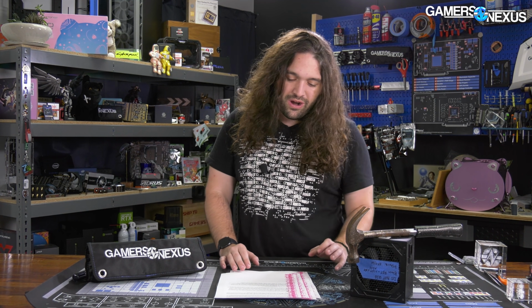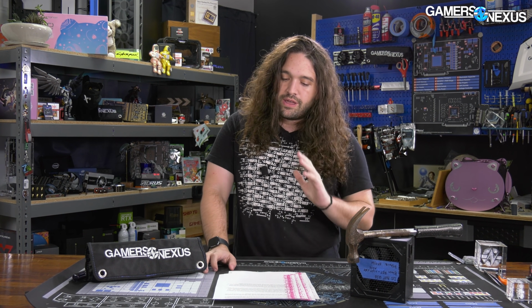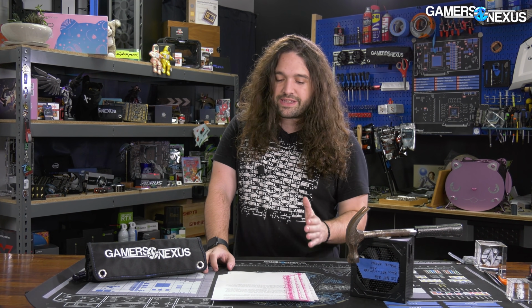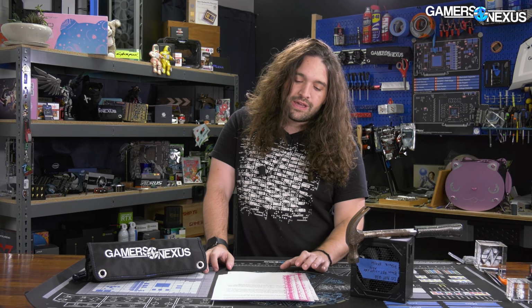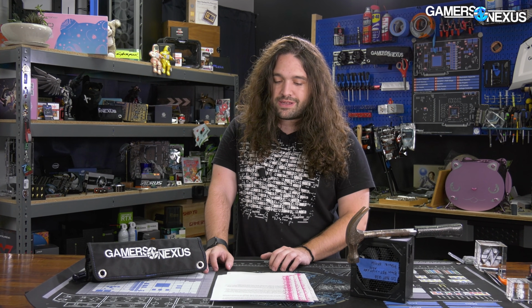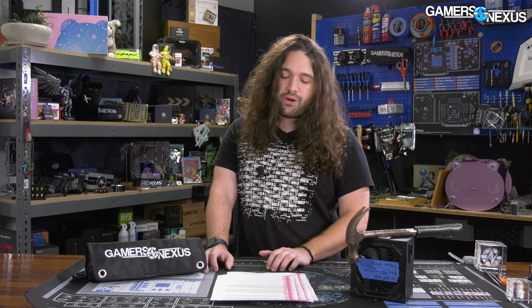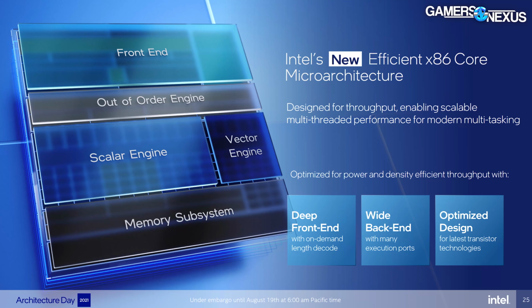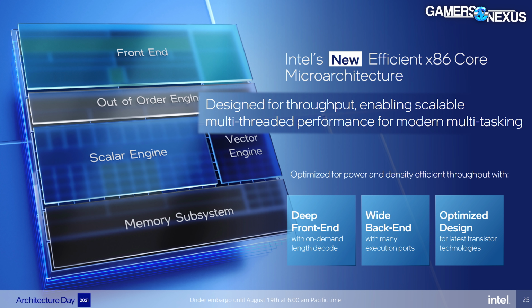Let's talk about the E-core. The switch from performance to efficient cores is somewhat drastic. So like the performance core, the Gracemont efficient core uses x86 architecture. They have this much in common. Unlike the P-core, though, it's designed for throughput and specifically efficiency with low power mobile applications and multi-core microservices. Intel's target was a small silicon area with the idea that more cores means more throughput here.